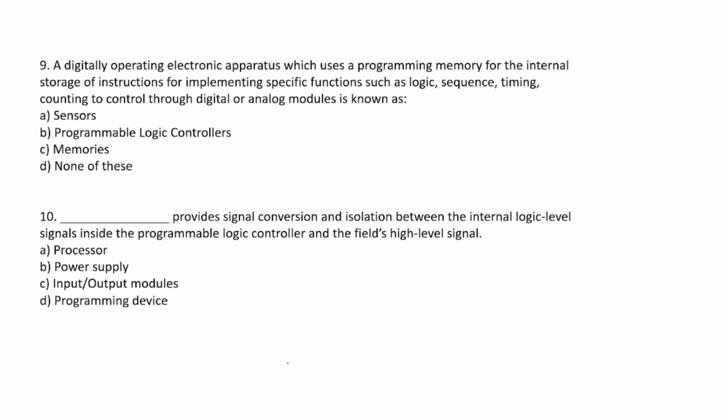Then coming to the next part, here the joint notations are given for those five arm and body configurations which we have talked about: articulated, polar, SCARA, Cartesian, and delta. The notations are used and the work volume is also given. For articulated, a partial sphere is the work volume.